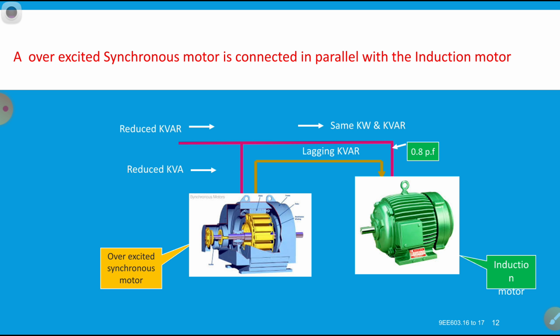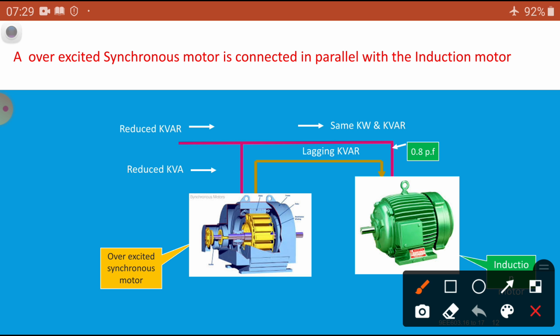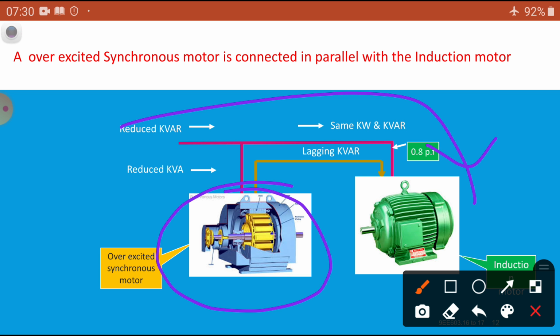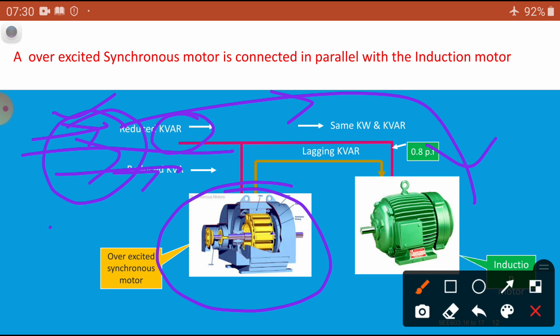Okay. So, we can see what is happening here. Under normal conditions, if there is no connection here, then whatever current is taken, the kVAr, the reactive power taken from the supply, increases. Then what will happen? That is supplied from the lines. So, the lines are subjected to the burden: overcurrent in the line, lagging power factor. The lines may heat up, more current will flow through the lines, and losses may take place. Instead of that, we can avoid it.